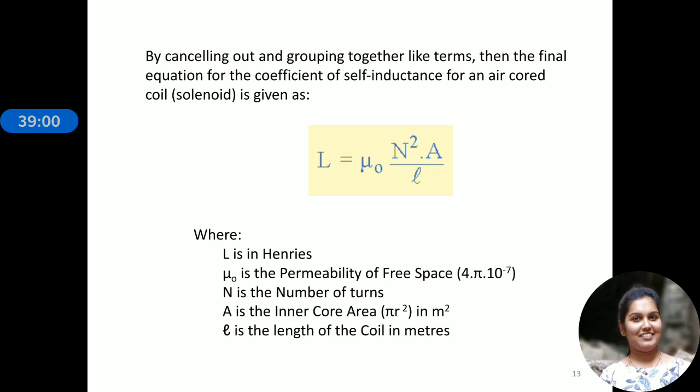This is because the material concentrates the lines of force more strongly through the soft ferromagnetic core material. That is what we discussed when we talked about electromagnetism, right? So that is why, because of soft iron materials or cobalt or nickel, we can see an increase in the inductance of the coil.